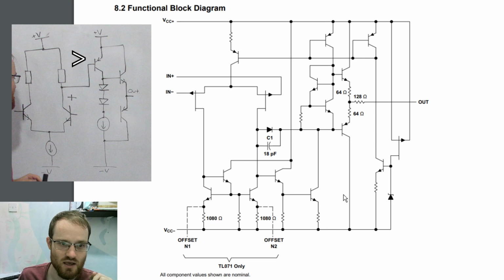This is our gain stage, right? So this is the common emitter amplifier. Here's our emitter resistor, and we've got all this stuff in the collector. These two transistors are acting like two diodes connected in series, which is what I showed them as in my circuit. If we look here, they keep these two transistors 2 VBE drops apart. So if we start at this transistor, we've got 1 VBE drop, 2 VBE drops, and then the other transistor.